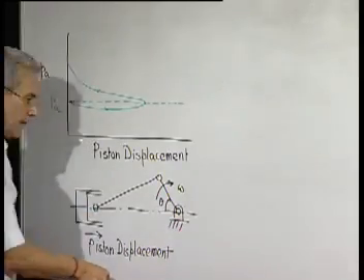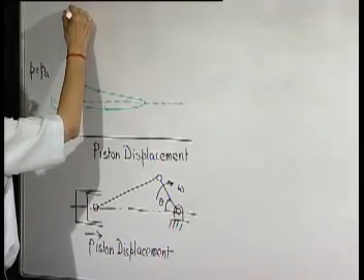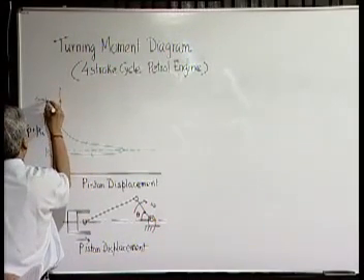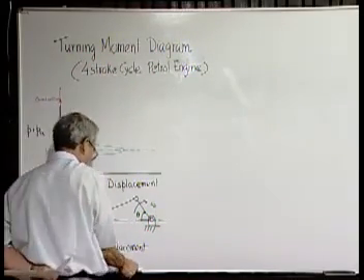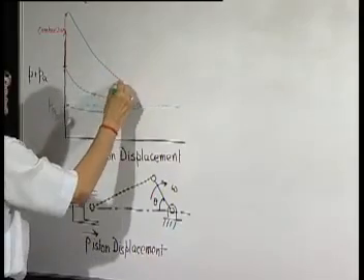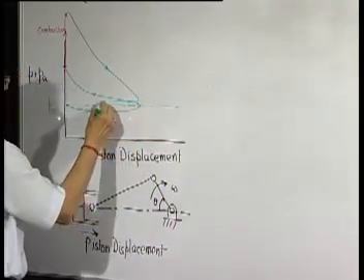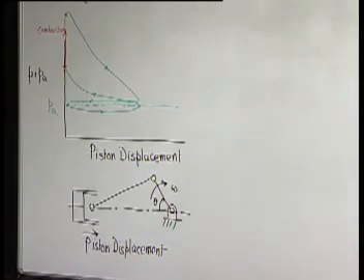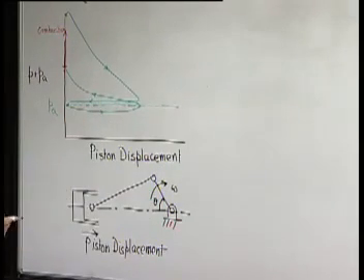Then there is firing, and this is the combustion. This is the firing. And next is the expansion, where pressure comes down, and the last stroke is exhaust, where again the piston pushes out the burnt gas, and to push it out into the atmosphere the pressure has to be slightly above atmospheric.